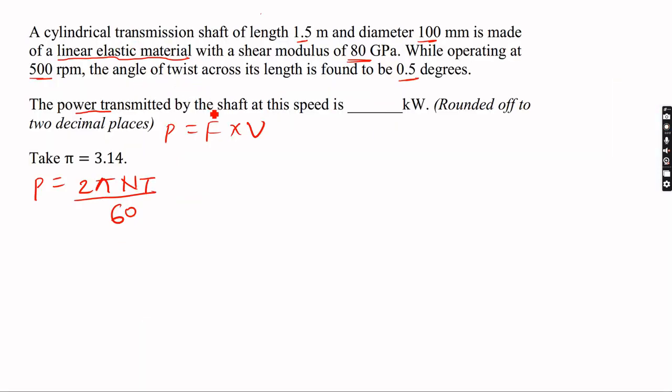Okay. So power is nothing but force into velocity. In basic mechanics, whatever you have read in 11th and 12th class, the same thing. Now, how are we reaching from here to here? You can simply write power equal to force into velocity. Also one formula you know: torque into omega. Omega is the angular velocity. This is radian per second, and this is meter per second. Okay, torque into omega is also your power.